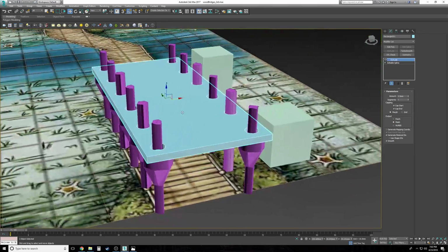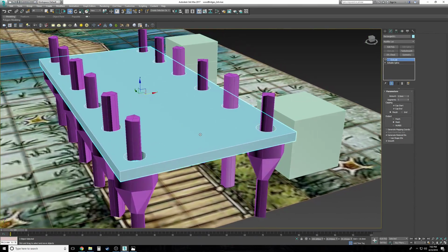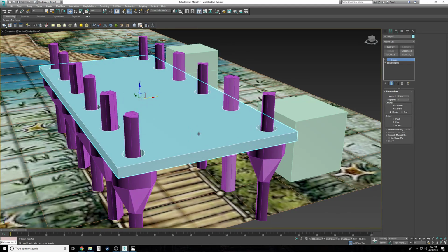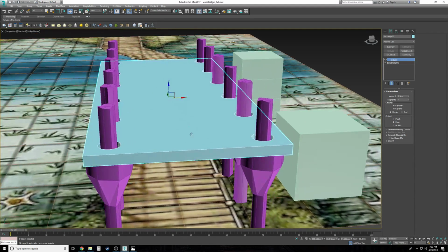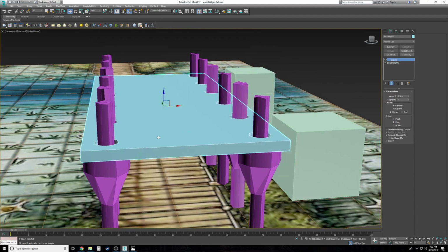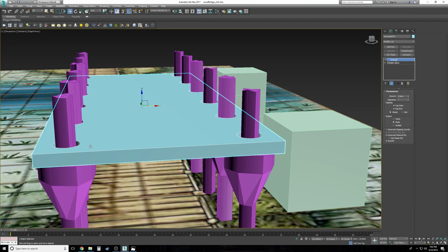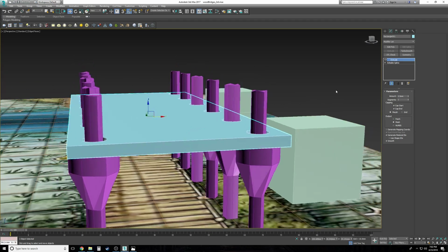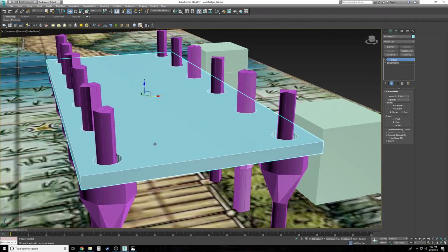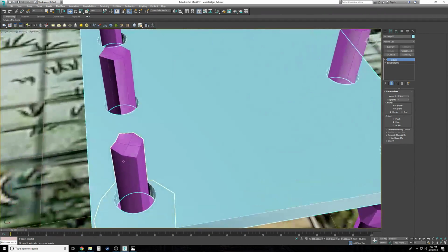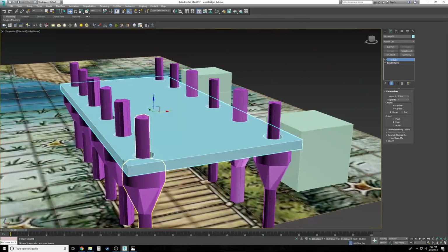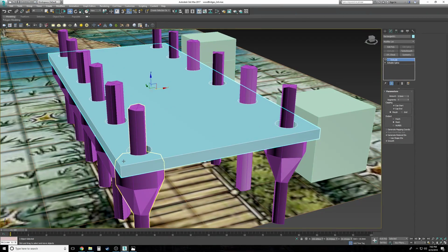And the top part here we're going to put planks on, so we don't really have to worry about it. I'm not going to worry about the holes because the planks are going to go in between separately. It's really going to start screwing up things if we start going crazy with adding dimensions to this hole, because these holes right here are precariously made in this object. So when we export it, it'll print fine, but we don't want to do a whole lot of geometric modifications.